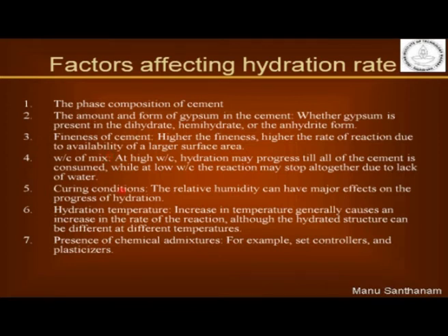Curing condition, of course, if you have very drying condition, you will not have any water present to hydrate the cement, it will start drying out. So that is why we need to provide curing to ensure that water has the chance to react with the cement to produce the hydrated skeleton, which is responsible for low porosity and permeability in the system.